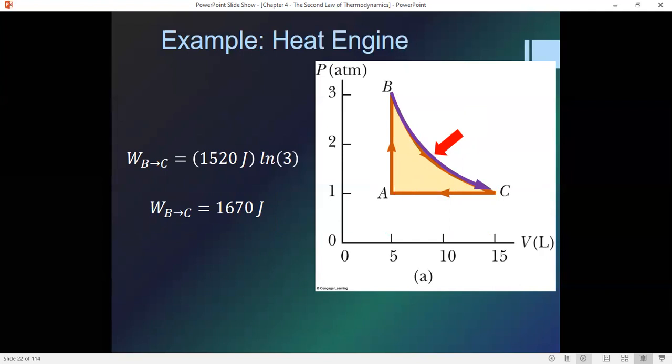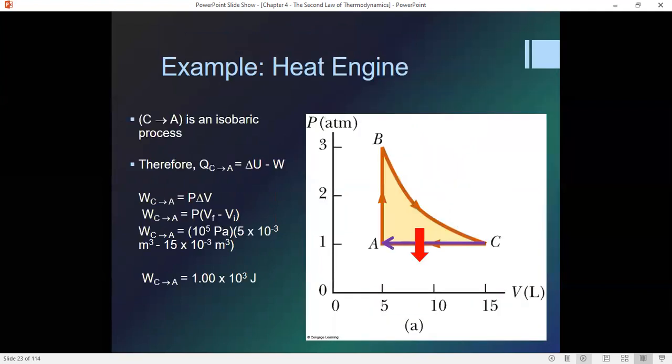So I'm going to undergo an isobaric compression. When that takes place, I am removing heat from the system because I'm going from 900 degrees Kelvin to 300 degrees Kelvin, all the while compressing that gas. Okay? Now, for this case, I again can calculate the area. Okay? And again, this is going to be negative area technically because we're going from right to left. So work equals P delta V. That's this equation right here.